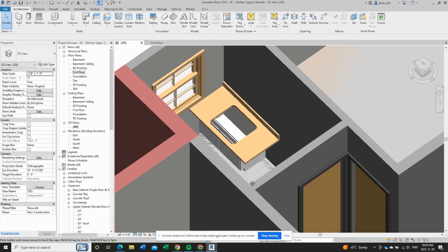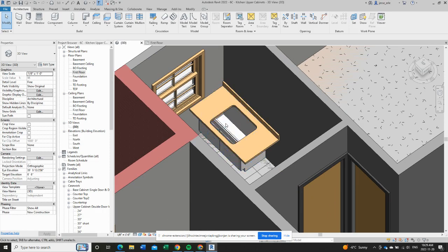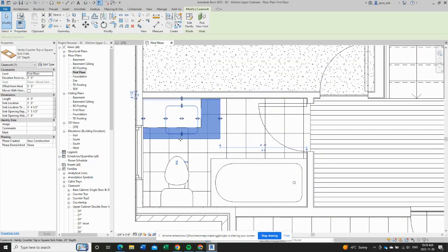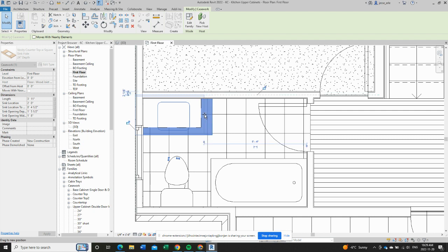So here we are. We've got the countertop on top of the vanity cupboard base cabinet, and we can see this raised area of the countertop. That's our backsplash that we definitely want touching the wall like it's oriented, but we know we need to make some adjustments to the size of this thing. So go back to the floor plan view, and this hole in the center, you probably know, is for the sink. I'm just going to roughly put that into position, and over here on the triangles on the right, we're going to grab that and just make it a little bit longer than our cabinets.